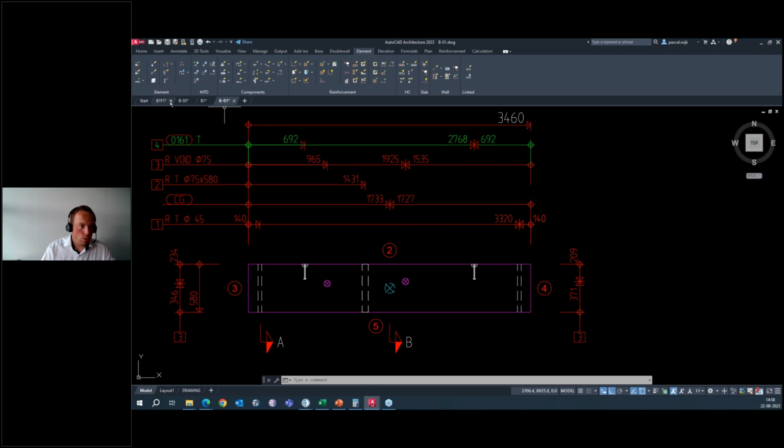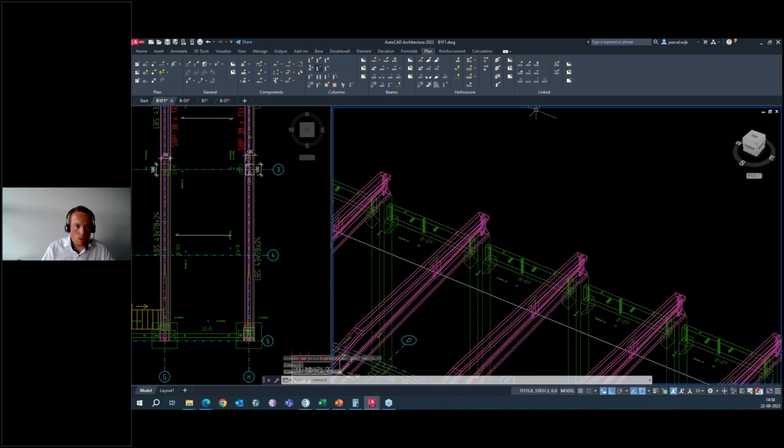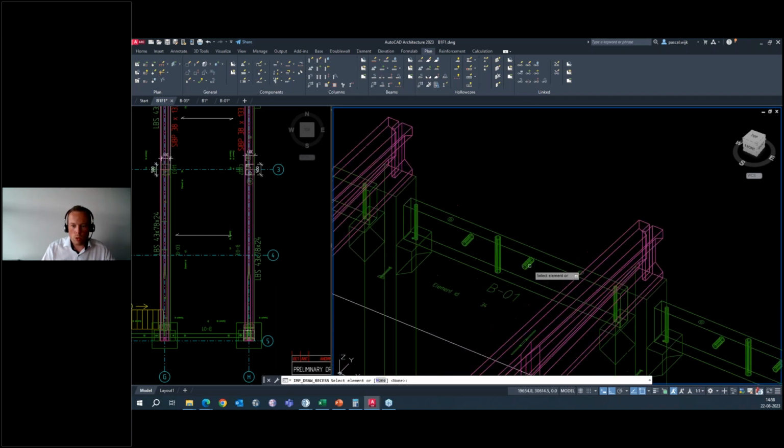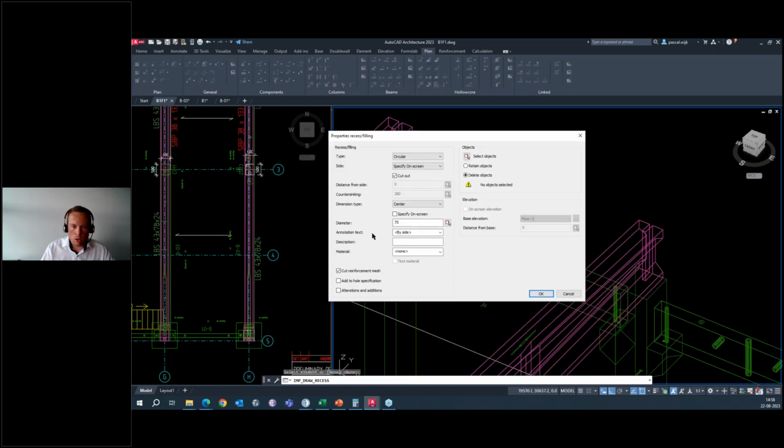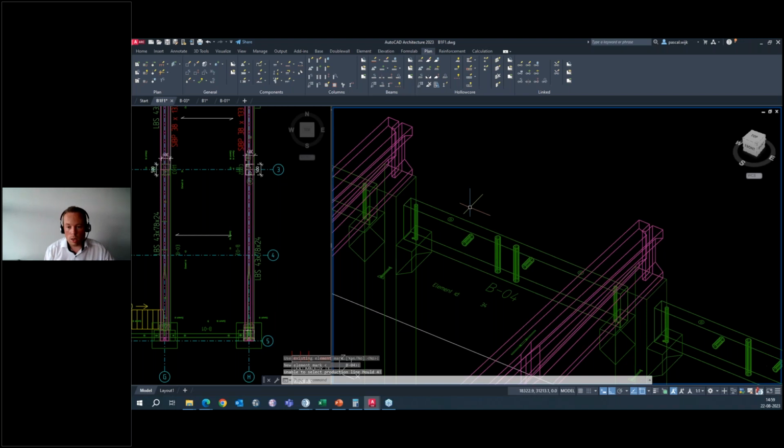No, not at all. But what you can do in that case too, I got this question there. If you don't want the element to get a new number, see, here is the button, use existing element mark. So what I can do is just click no. And what Impact is asking me is, do we want to have a new element mark? So in this case, I'm just clicking yes, and this element is getting a new element mark. So that's actually that easy.